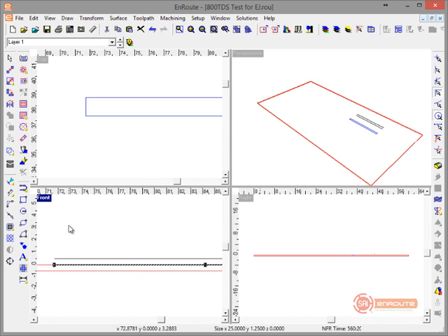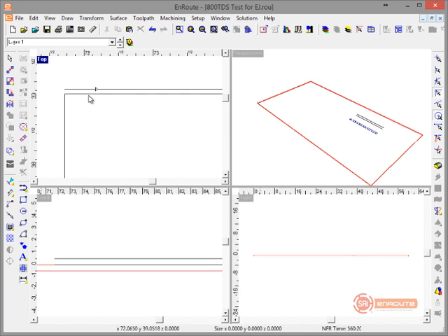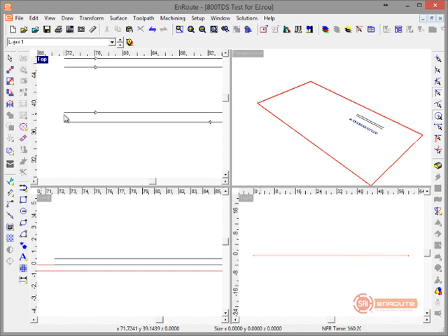All right, now when I do this offset, I'm going to need to offset 0.0625. Maybe just make it easy on myself and say 0.07. Alright, now I should have accommodated half the diameter of the bit there.